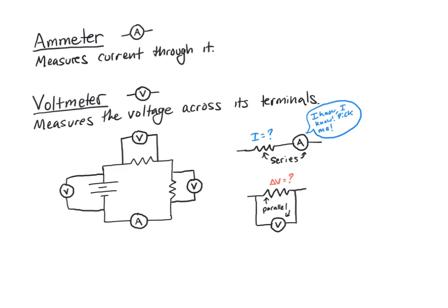Parallel here doesn't just mean, oh yeah, they're drawn as parallel lines, cool. No, that actually can get you into hot water. For example, I can have two resistors that are drawn parallel to each other, despite being in series with each other. And I can draw two resistors in parallel with each other, despite being drawn in line with each other. I think it's straightforward to see that these two resistors are not in series with each other. The current from the battery is going to be split two ways between them. Because they don't necessarily have the same current, the current isn't forced to go through one and then the other. These are not in series with each other.